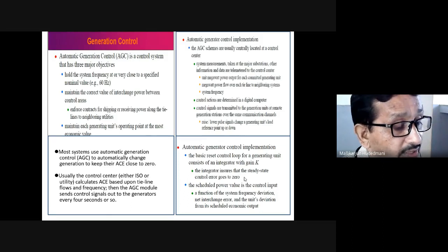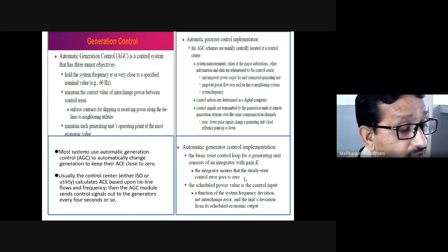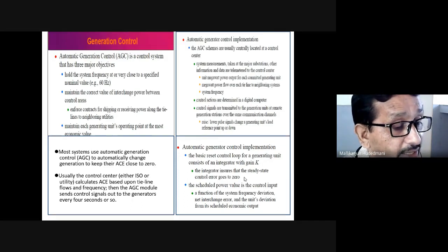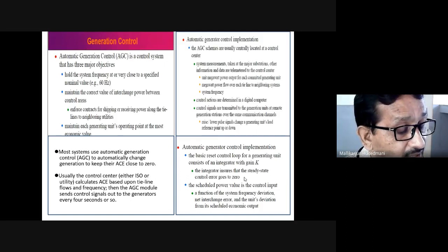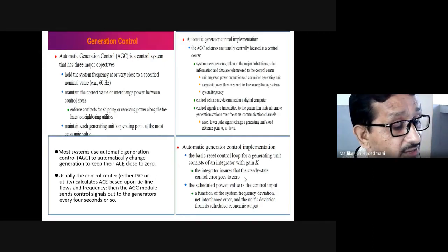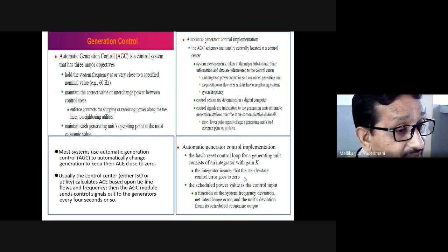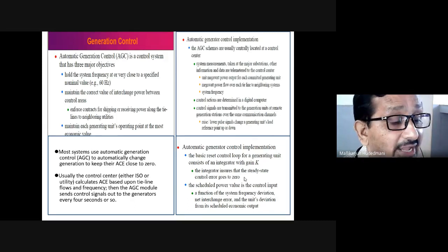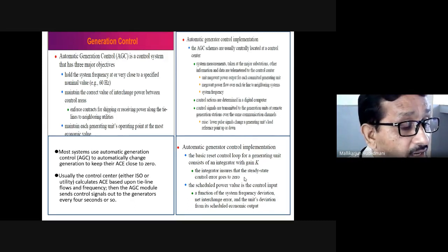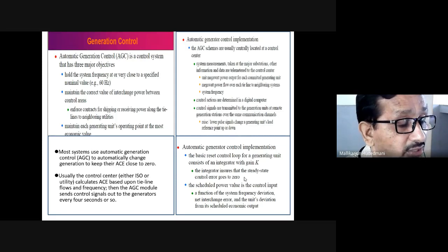The automatic voltage regulator tries to regulate the field input supply to the synchronous generator, monitoring the input to the field coil, so that the field poles are magnetized appropriately and the developed voltage is at your required line voltage. We call it automatic voltage regulation.